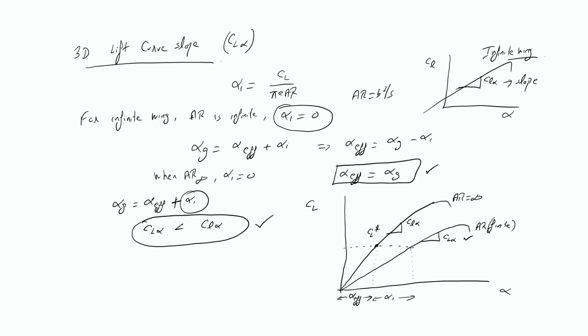Okay, fine. Now this was applicable for symmetric. We'll come towards cambered as well, but as of now, first of all, let us find the relation between the Cl alpha and small Cl alpha. Okay. So now when aspect ratio was infinity, Cl star can be written as, remember the equation? Cl equals Cl naught plus Cl alpha into alpha.